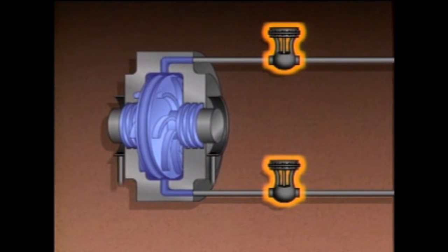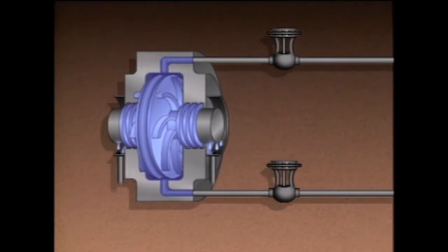Valves in the water supply and return lines maintain the proper water pressure in the gland. This design allows some water to leak out of the seal. For this reason, shrouding is placed around the turbine shaft on each side of the seal. Water collects in the shrouding and is drained off by connecting drain pipes. As with all turbine systems, sealing systems should be regularly checked to make sure they're functioning properly.